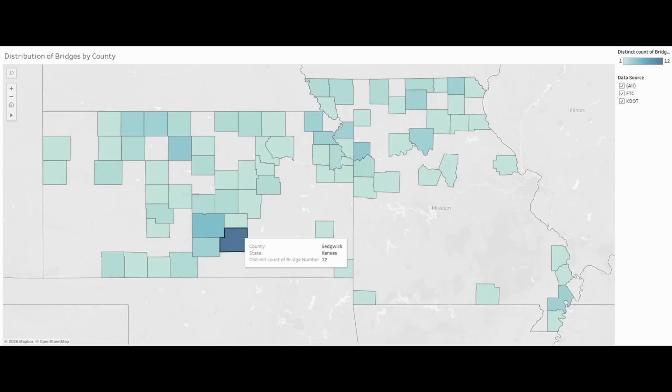So that we could say, for a given type of subsurface material, you would expect the pile to go into a layer that has this compression wave velocity to develop the required capacity. And so I'll cover more about both of these as we go forward. So this figure is from our data analytics package.